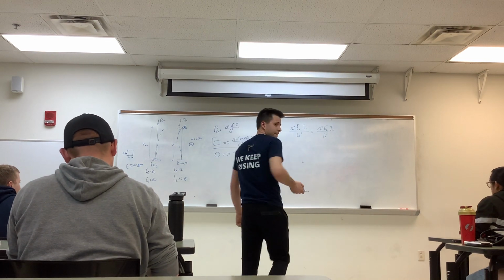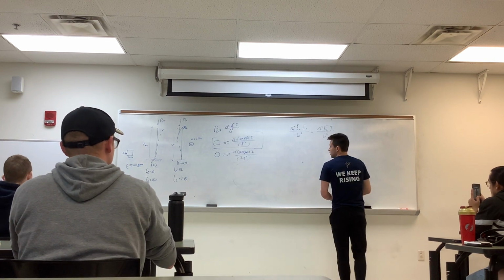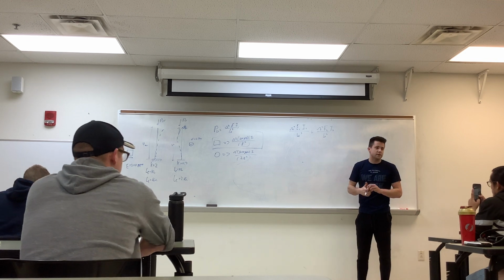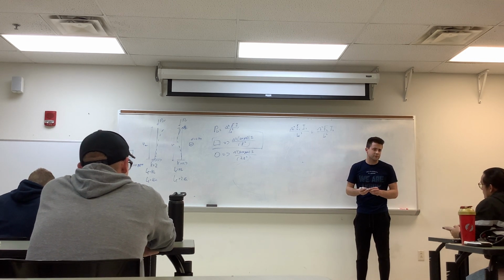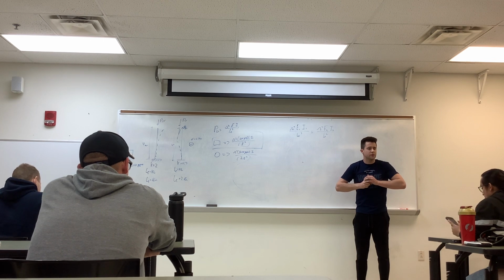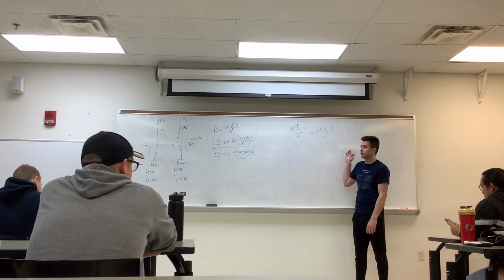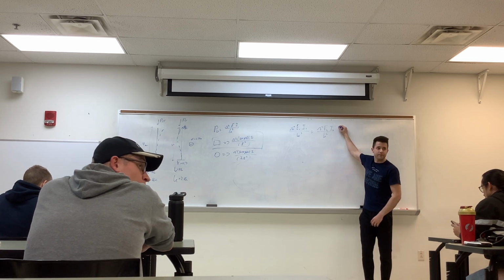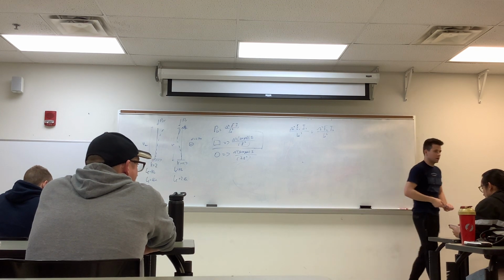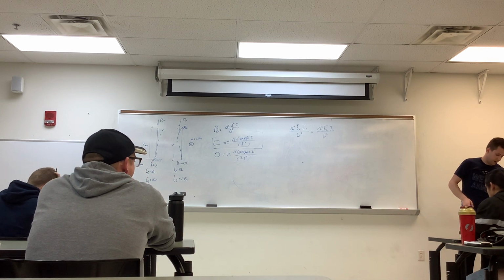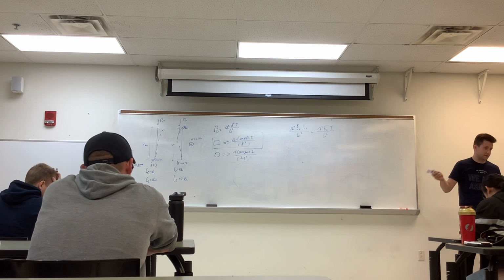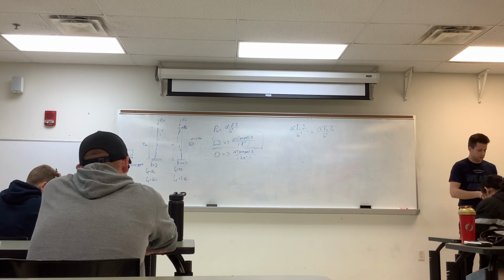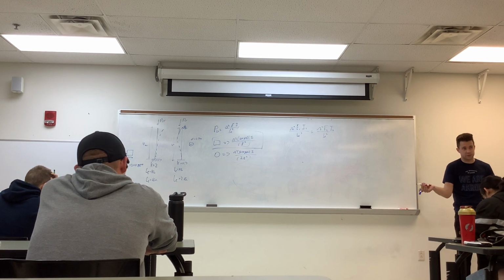Okay. And so you take those two equations, those are two different, I guess, poles or whatever you call them. Yeah. And then you set them equal to each other to find the inertia if you're given the elasticity. Yes. You can find different values. When we did these, you're just assuming all the other variables would be equal, because the critical buckling between the two would be the same, so you can make the two equations equal to each other. Okay.